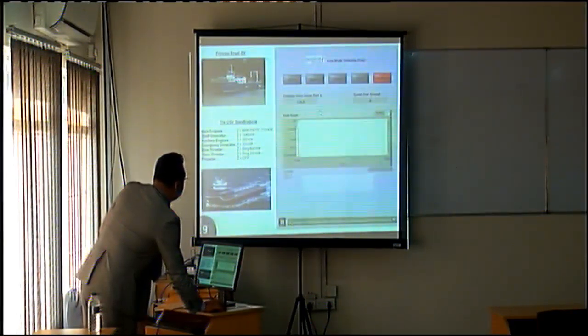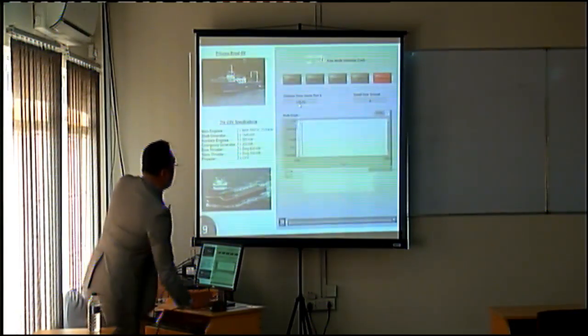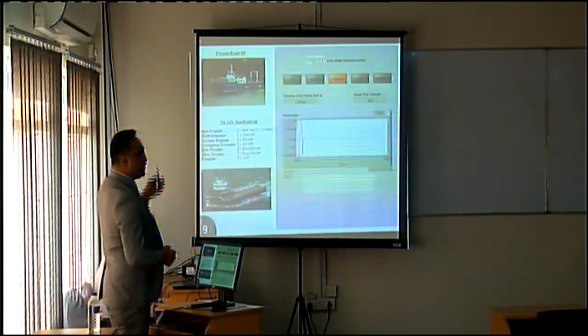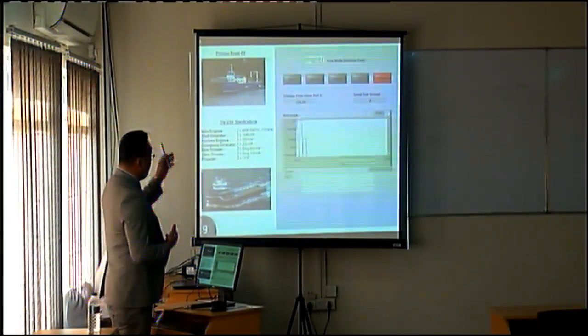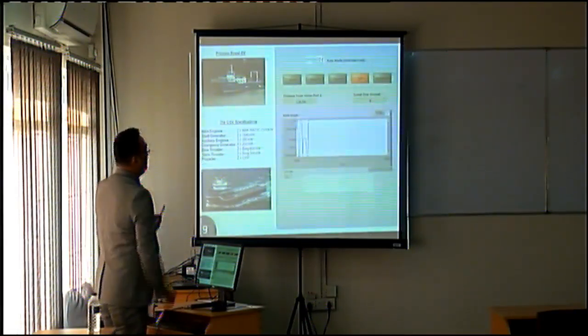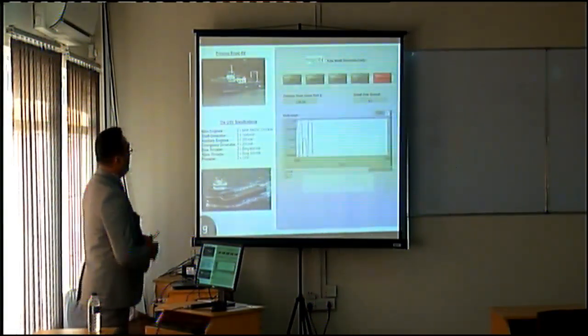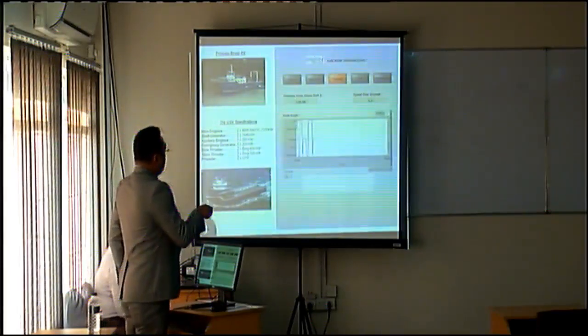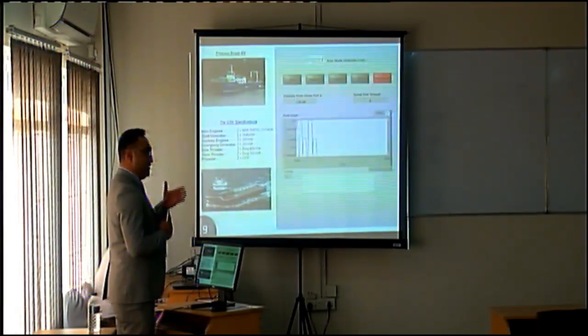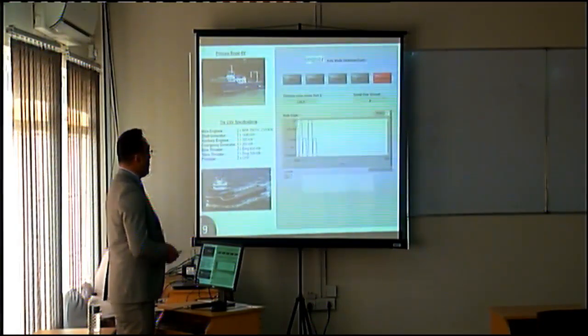The sample is running at the moment, and this is the distance from the home port, around 130 nautical miles. You can see that when the speed changes, it matches the fuel consumption and the mode profile. Every time, the mode changes. Now we have switched the mode to DP. You can see almost the same distance, so it doesn't move. It is close to the rig.